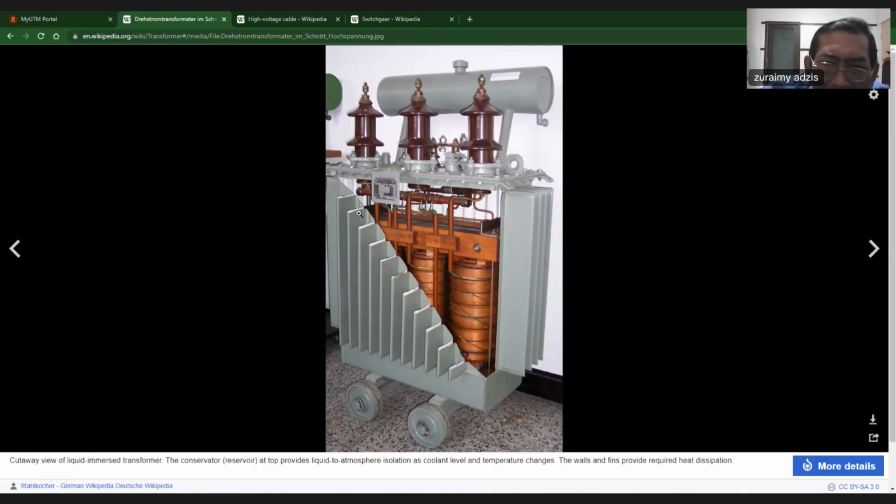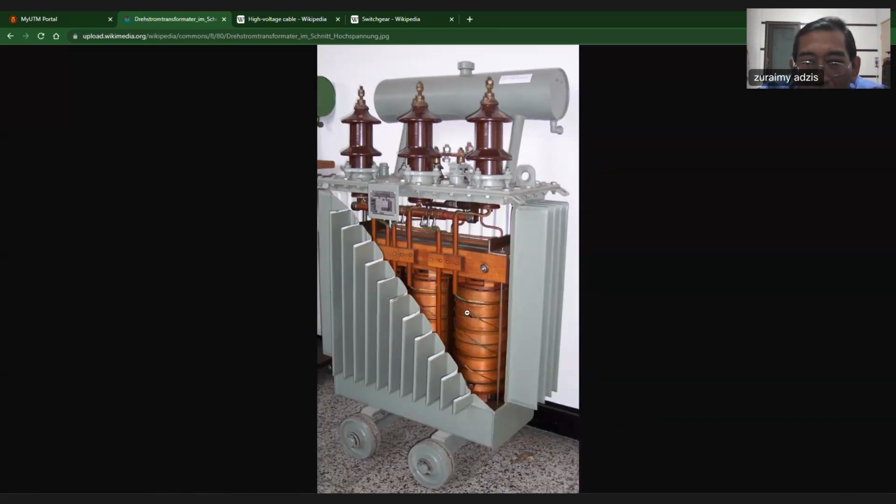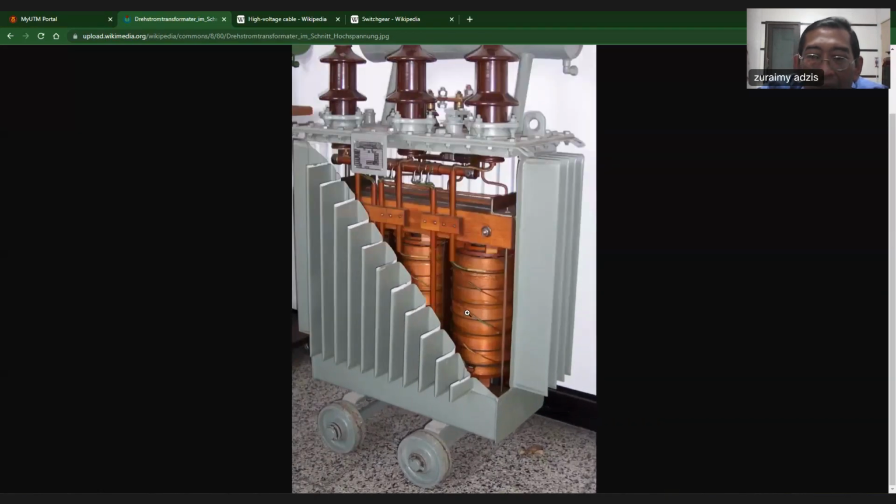And within these high voltage coils are the lower voltage coils, and their terminals go up to the lower voltage bushings. Everything here, okay, there you can see an orange color, but actually it is paper. All right, paper when immersed in oil becomes sort of this color. If I can zoom in further, oh, that's the best I can zoom. And these are windings, all right. And all these windings are insulated by paper, so that windings don't short circuit each other between phase 1, phase 2, phase 3, or maybe phase red, yellow, blue, or A, B, C, whatever, doesn't matter as long as it's 3 phases.